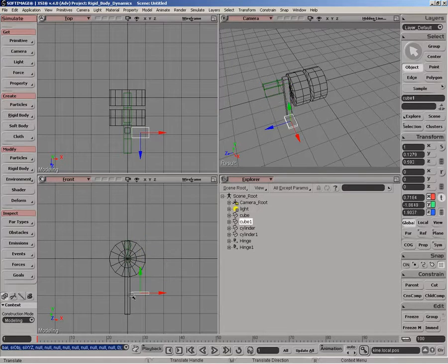So what we're doing is going to basically create a little gap that the leg arm can fit through, and it'll just bang against those. And the tighter the gap, the more we'll just see a vertical motion. The wider the gap, the more it'll have room to swing horizontally, and the wider the step. So what we want to do is create an optimal balance between the actual vertical motion and the horizontal motion.